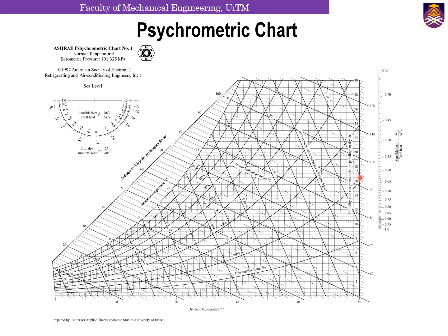So this is the psychrometric chart. This is how it looks. I would like to bring your attention to the first important point here. If you want to use this psychrometric chart, you must make sure that your pressure is 101.325 kilopascal. Any pressure besides this pressure, you will not be able to use the psychrometric chart. 100 kilopascal is not 101.325 kilopascal.